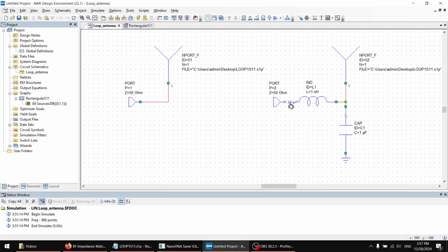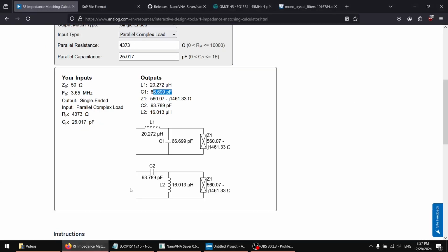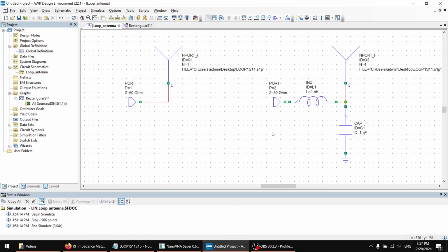Now, what you might be asking me right now is why we have these suggestions of two circuits. The reason is that this will have a low pass characteristic, and this is just an equivalent circuit with replaced components, and this will have a high pass characteristic. Later on, I will show you more complex structures that combine low pass and high pass circuits to create a higher bandwidth of this matching. But here we care about something simple and quick.